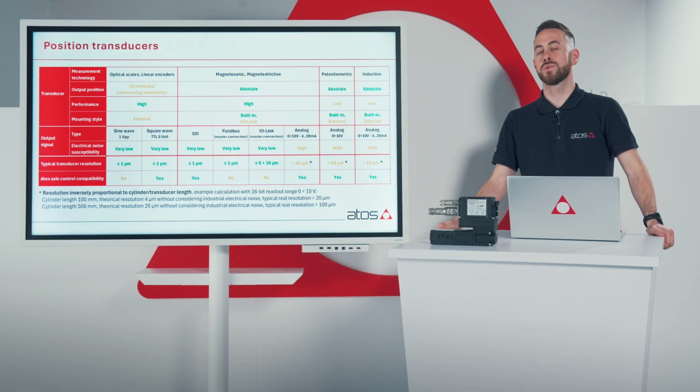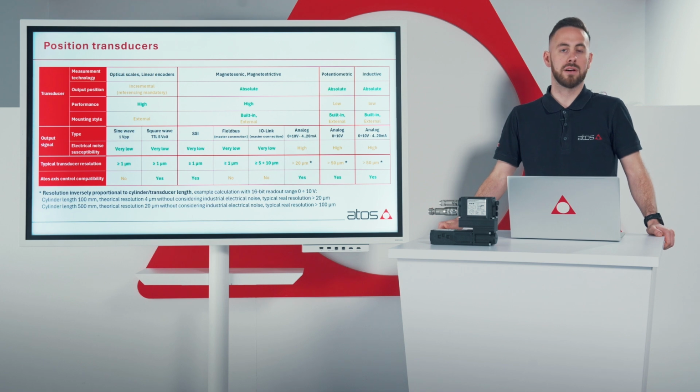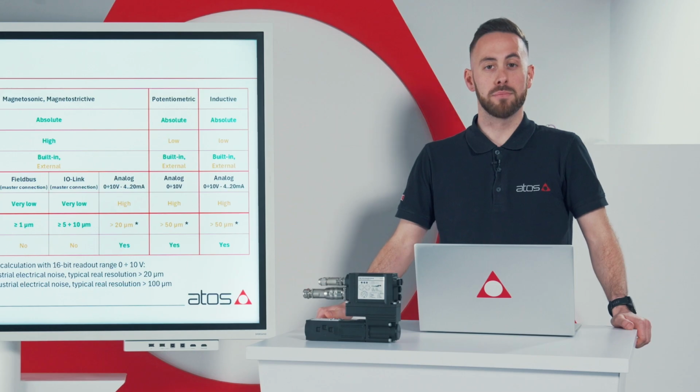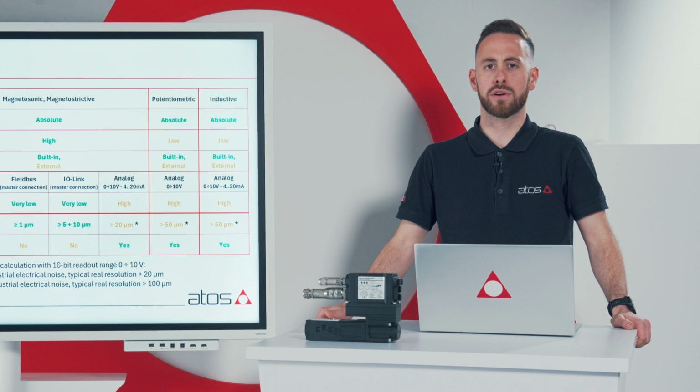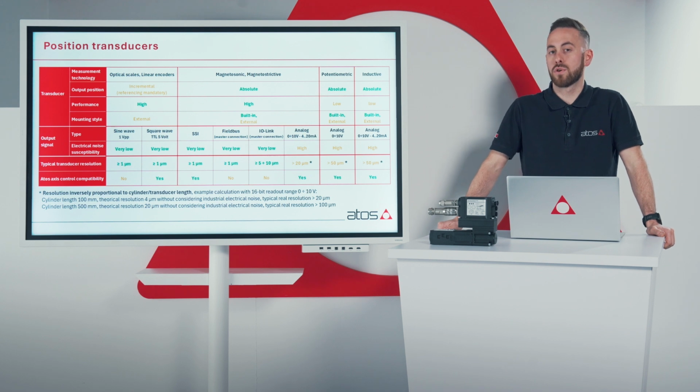Voltage analog transducers are used for short wiring runs, where the voltage drop does not affect the feedback signal. For cable length greater than 20 meters, we recommend use 4-20 milliamps analog feedback transducer. Additionally, one advantage of the 4-20 milliamps range is that it allows detecting potential cable broken condition and ensure safety on the system.